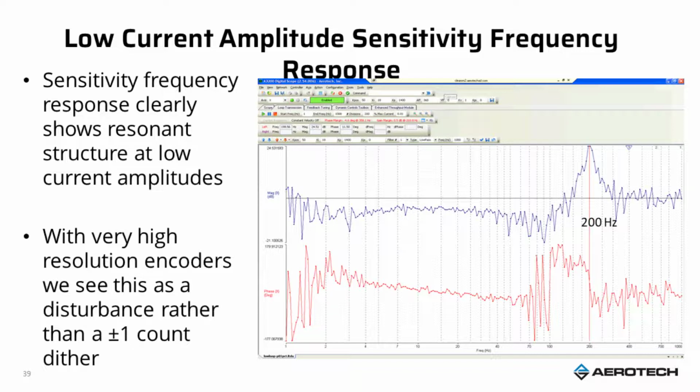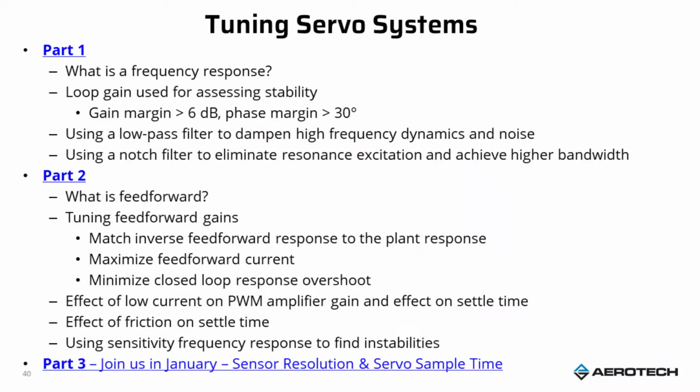So the sensitivity response I find very useful for looking at robustness of the system. You'll see instabilities that look like peaks, like the one shown here, much more easily in this response than you sometimes will in the standard loop transmission.